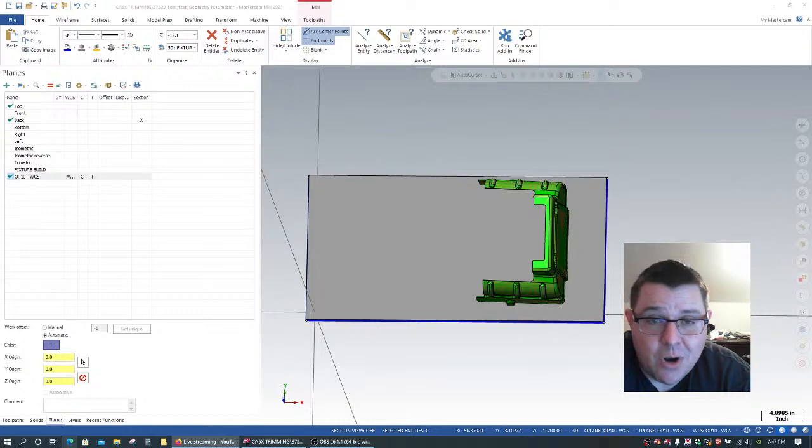So really, we start with the part itself, analyze what we've got, fix it if necessary, and then we start moving it in position and using geometry tools to start building lines and arcs and planes and rectangles, and then cylinders, and we start extruding those things to start building the actual fixture that we're going to design.